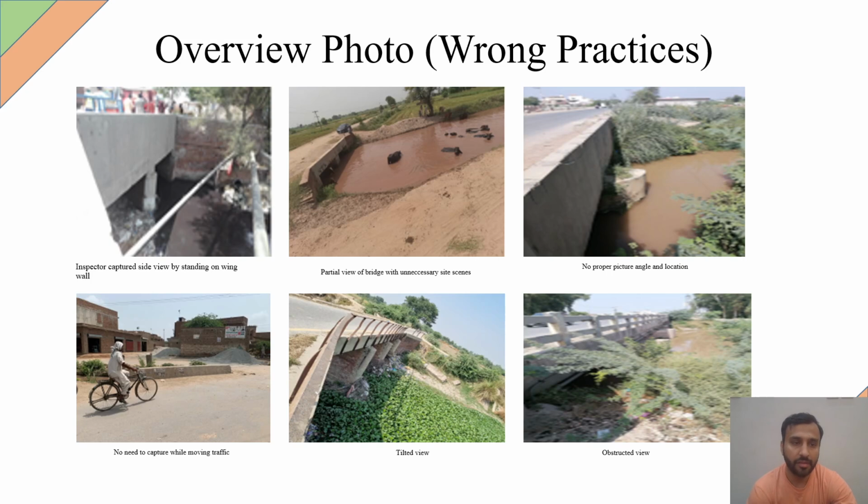I was mentioning that the inspector should capture a side view by standing on the wing wall. They should go a little beyond the wing wall and capture a complete side view of the bridge, because otherwise it is not indicating the full condition of the side.